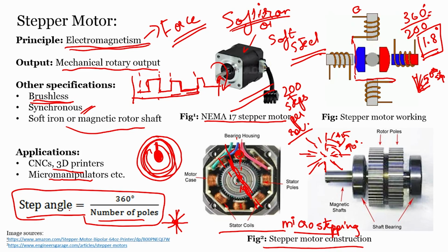There is a high and a low for a certain duration. So, this is a pulse. When the motor driver A4988 gets a single pulse, it will count it as one step. So, you send a single pulse, it will rotate one step. If you send another pulse, it will rotate another step, and based on the direction pin or the direction signal that you have given already, it will change the direction also.